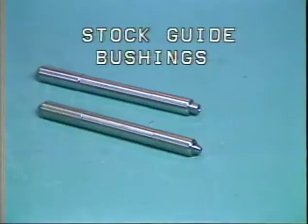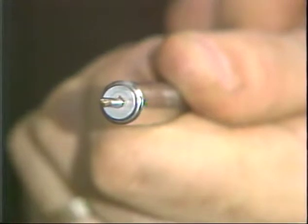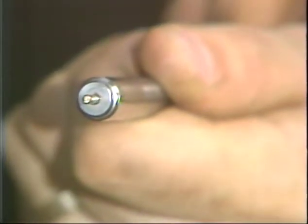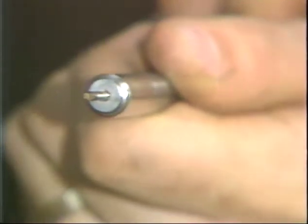The stock guide bushing is changed to meet the size stock used for the job. Each bushing is marked with the size stock you can feed through it. You must check the bushing with a piece of straightened stock of proper size. The bushing should support the stock with no play between the bushing and the stock. The bushing should not cause the stock to bind or stick.